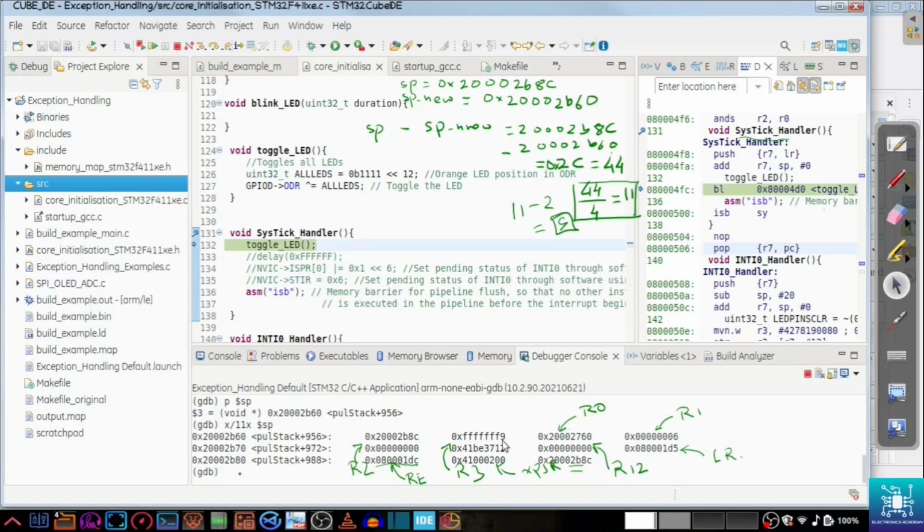So you can actually corrupt the program if you load this kind of a value into the PC by any chance. So be careful. Whenever this value is seen, the controller assumes blindly that it is a return from interrupt. You can fool the controller into believing that it is going back from an interrupt if you put a value like this into the program counter, and it will fault.